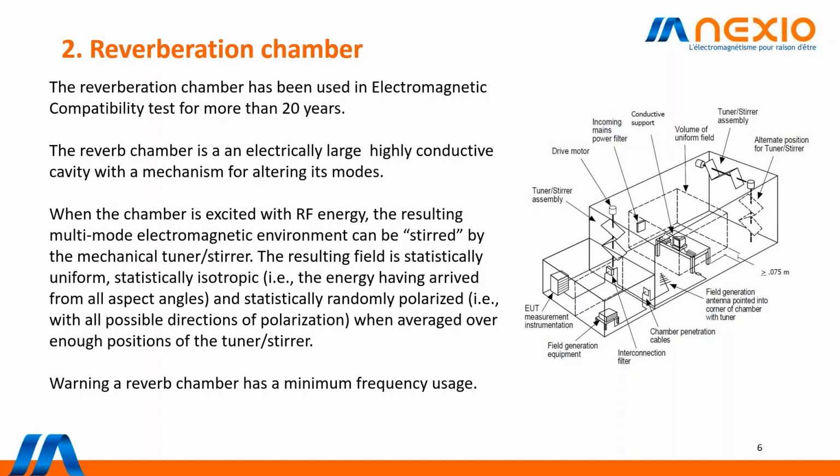Warning, a reverb chamber has a minimum usable frequency, which means that depending on the frequency, you're going to have to make your chamber bigger. Generally, the minimum frequency is between 3 to 5 times the f0, which is the first chamber resonance.